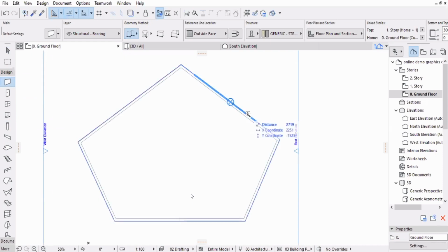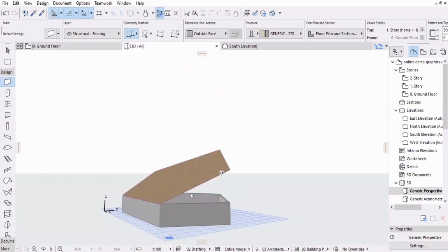When you hold down your space bar, it will give you feedback like this. That is, the wall is going to be of this shape. You can just go and hit click, and then see it has drawn walls exactly in line with that, right?